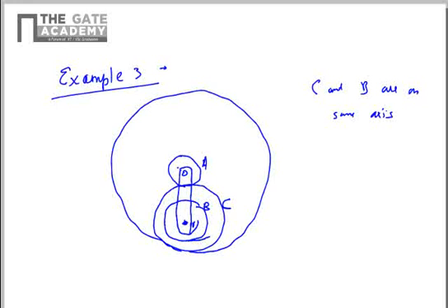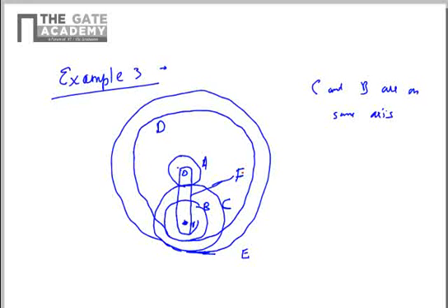Now gear B is made to mesh with another internal teeth annulus, termed as gear D, the internal teeth. And where C is rotating on this annulus gear. This annulus gear is termed as E. So you can see there are a lot of gears here, and then we have the leg also, the epicyclic chain. The leg is termed as F, which is the arm.